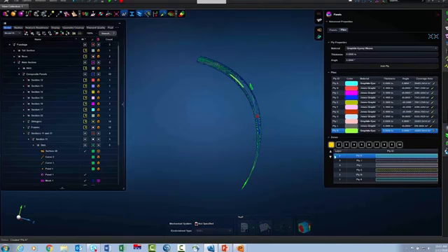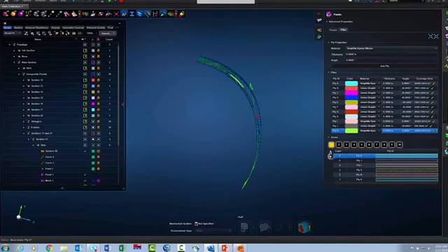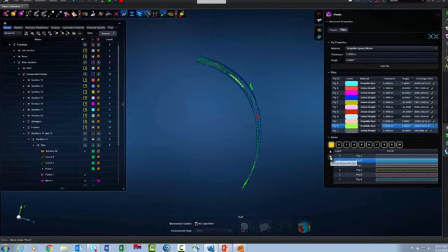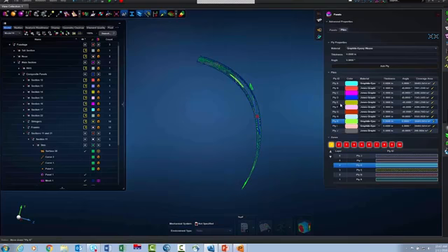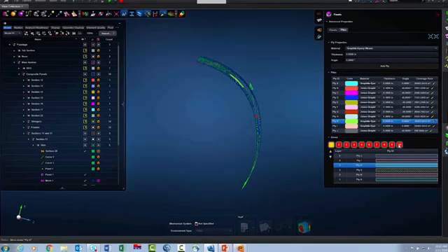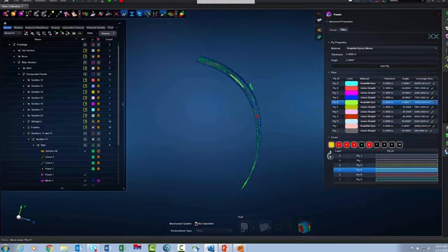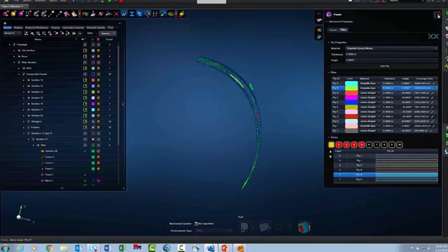It's very easy to reposition it. I'll just come in here to any particular zone that contains this ply, and I'll just reposition it. Notice how it's going up. Notice how I'm getting feedback that I'm modifying a lot of zones in this case because this ply is actually in every zone, so I expect to see a lot of modification. And I just keep moving it until now it is in its proper position.